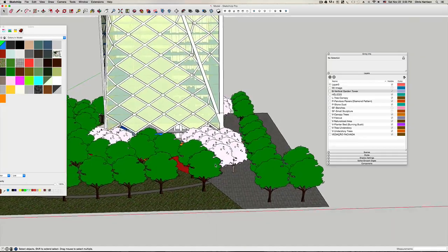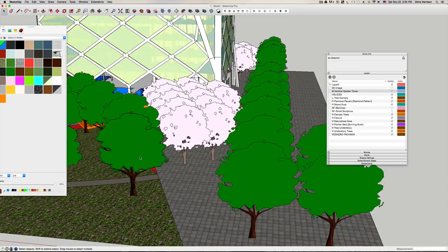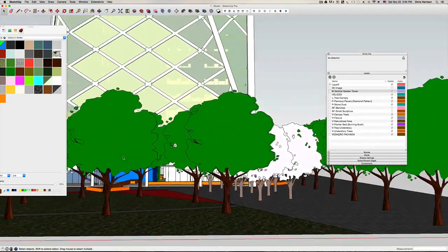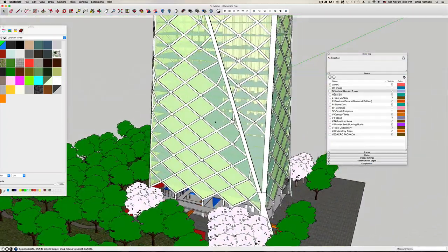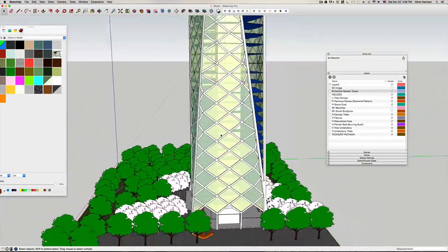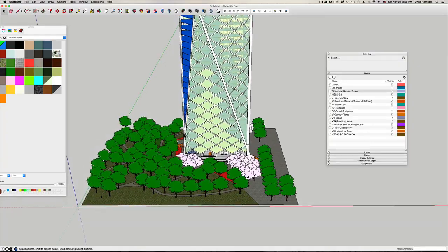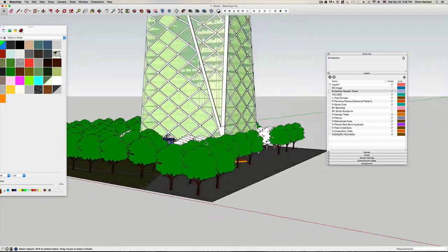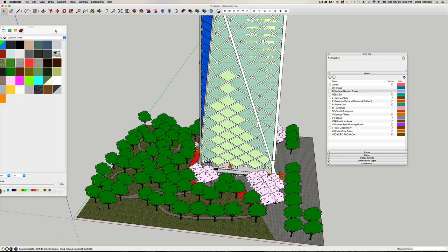Alright. Now once you have your elements there and all that, you can play with the colors and you can change some things out. If you want to change your trees out, you can, just make sure that it's a 2D face me. And it's just using the same principles, but keep the building there so we have some kind of frame of reference for everybody's work. Okay, so that is the first part of bringing it into SketchUp. And now once you have that kind of set, and again you can play with these things, you can export it into Layout to print this thing out.